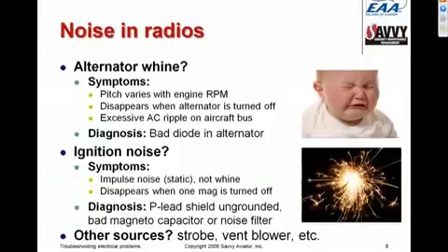Each of our spark plugs has a noise suppression resistor in it, and there's a history of those resistors, particularly in Champion brand spark plugs, going bad, and that can cause ignition noise as well. But the first step, of course, is to verify that it's ignition noise and to isolate it to a particular magneto. And then the first thing to look for is an ungrounded P lead, and if that's not the problem, then you need to look a little bit further.